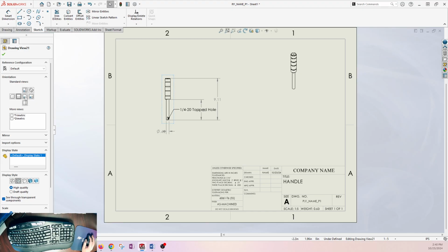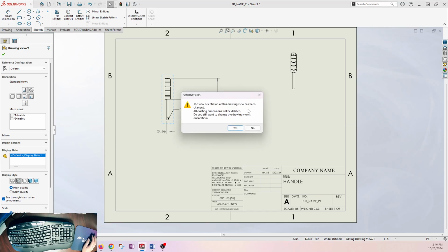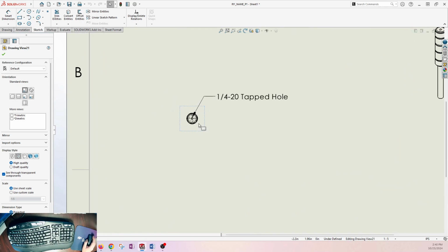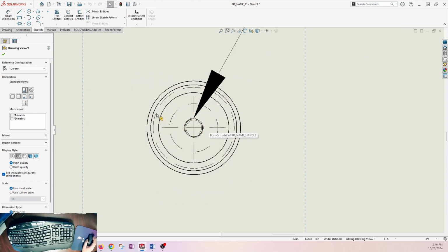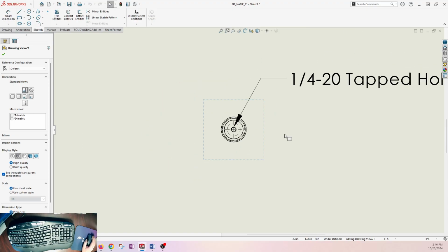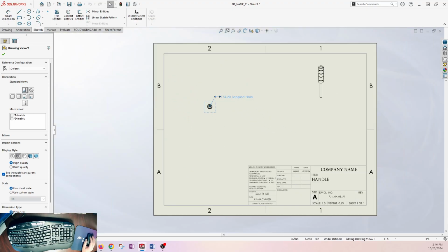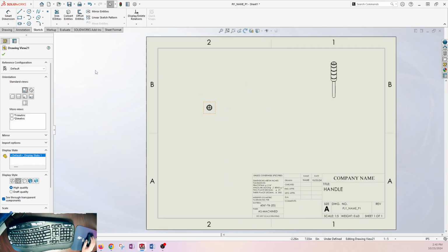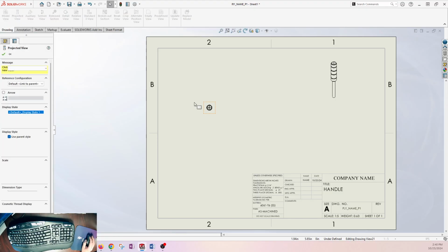If we were to show, yeah, just delete it. I don't care. Okay. If we were to show an end view, I think that's the correct view. If we're to show the end view and then project it, we go to Drawing tab and we project.